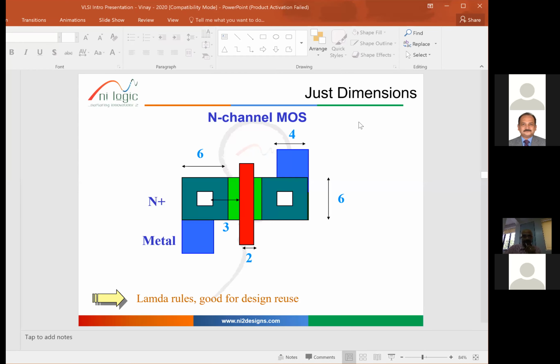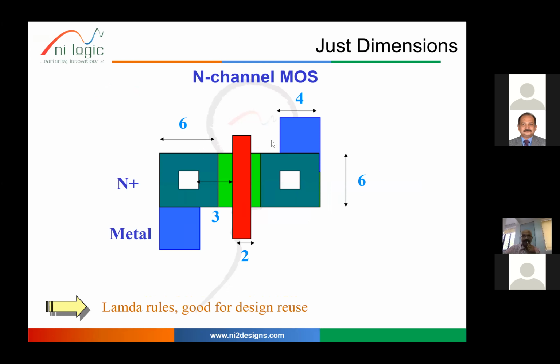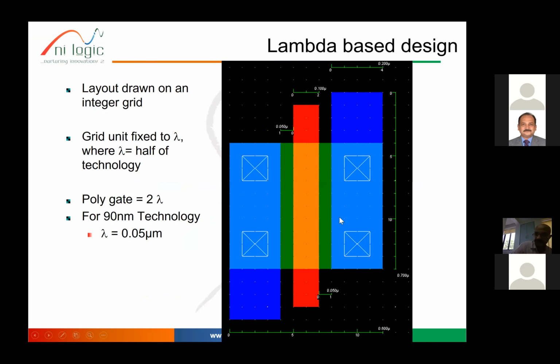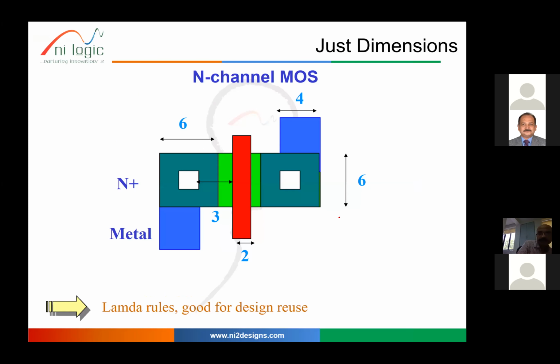So here, do you see that is nothing but an NMOS transistor. The same thing we have drawn just now. So you can just draw a metal block like this and a green block. This is the green block we made, the green block for the n-diffusion. And this was a metal block we made for the metal layers. And this was a polysilicon block in between we made for the polysilicon gate material.